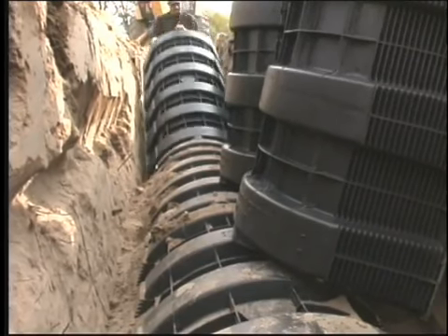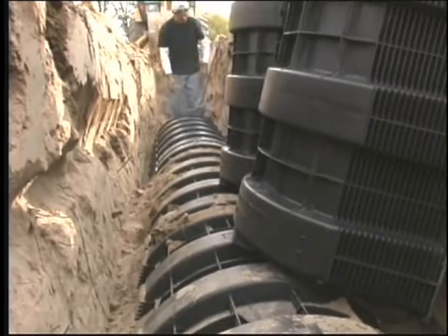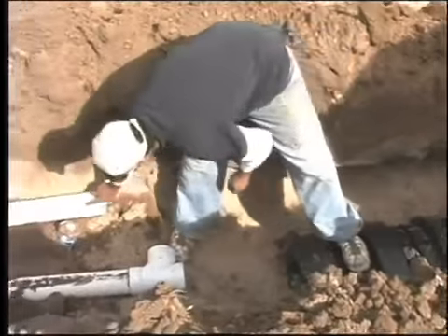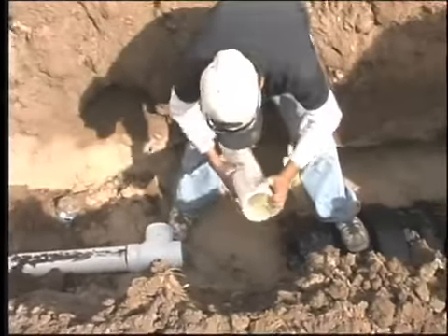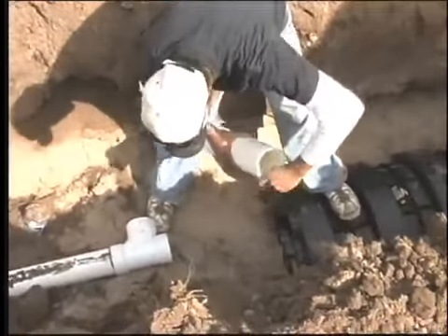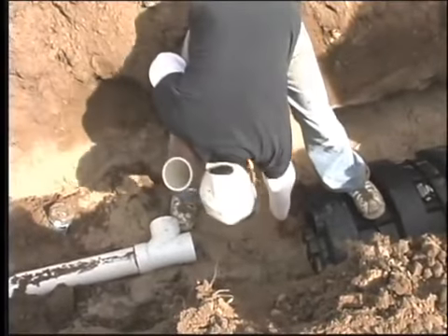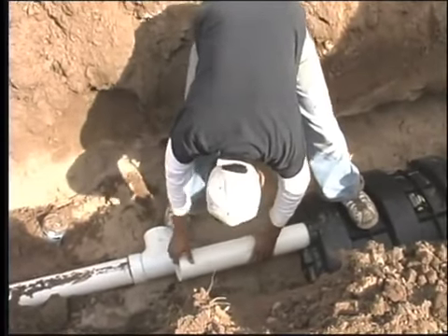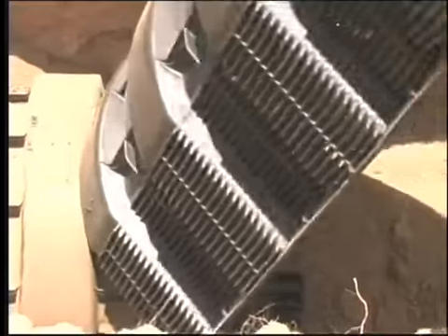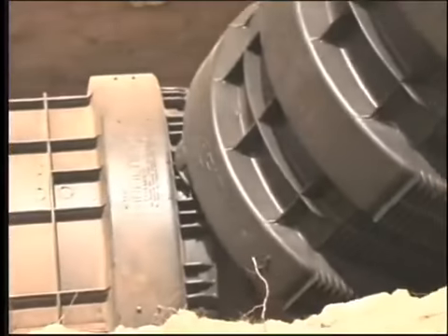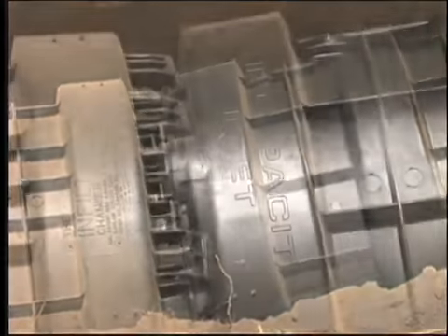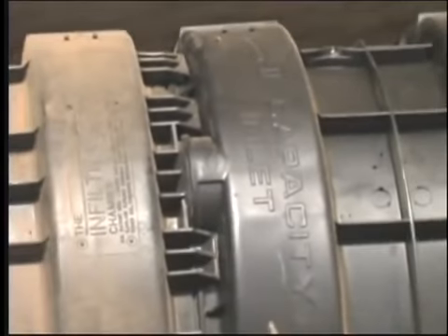Place the pipe through the inlet opening and position it so the end of the pipe is over the splash plate. In a chamber drain field, the pipe brings the water into the system but does not extend into the system. Connect the remaining chambers together to form the desired length of the trench. Ensure the interlocks are fully engaged. You may also choose to screw the joints together.